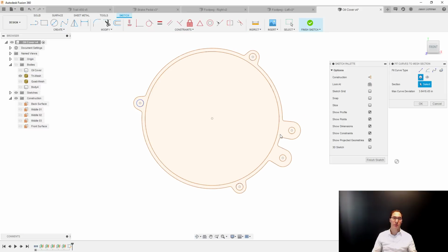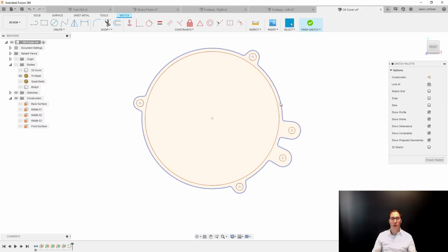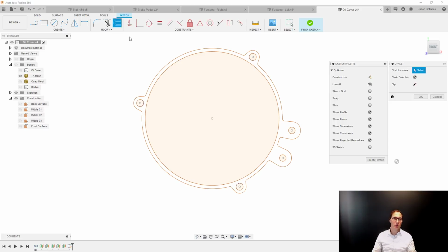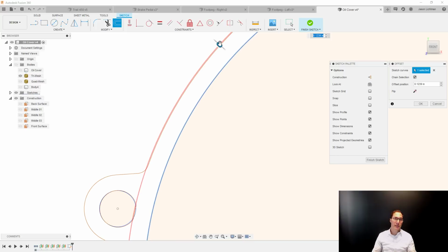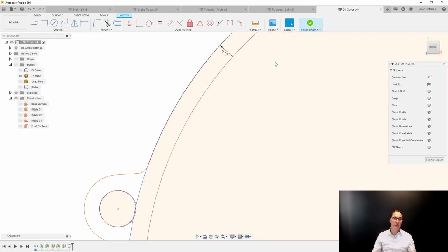And those are looking really good. Or maybe I want to take that outer shape and I don't want to just use this as a spline, and maybe I want to recreate it. Well, even then I could delete this, and keep in mind I could still use my other sketch tool, like offset. I could choose an offset, approximately that amount, start to zoom in a little bit and see what this value should be. And maybe based on this, it should be 0.12 and leave that there.